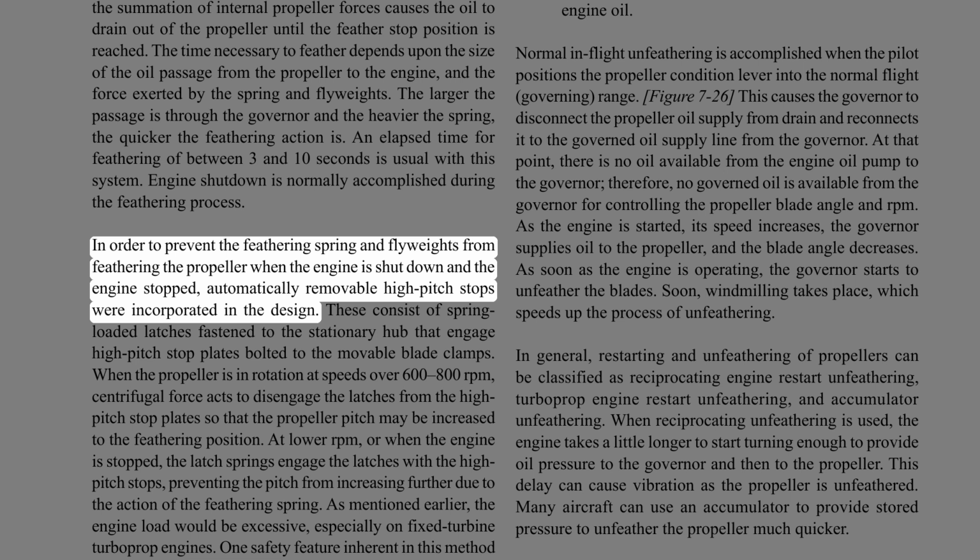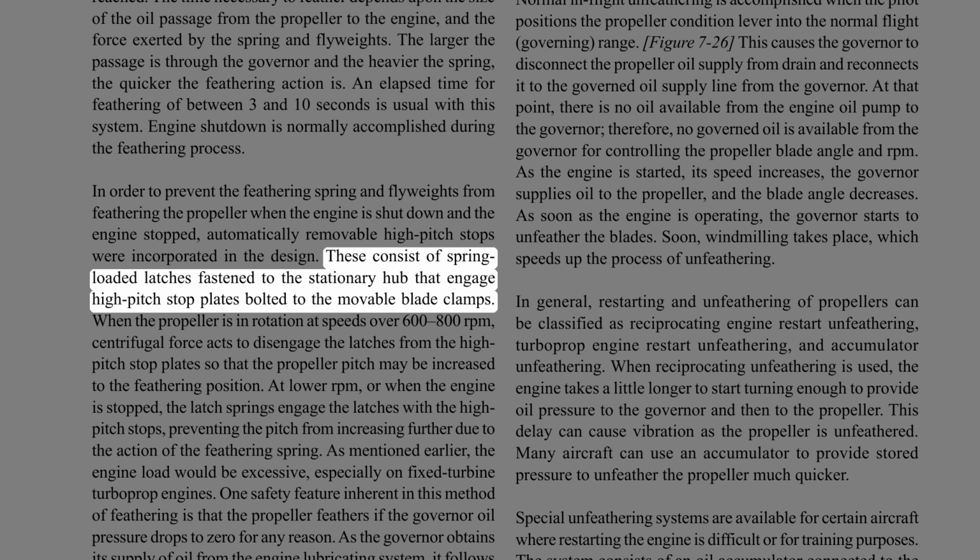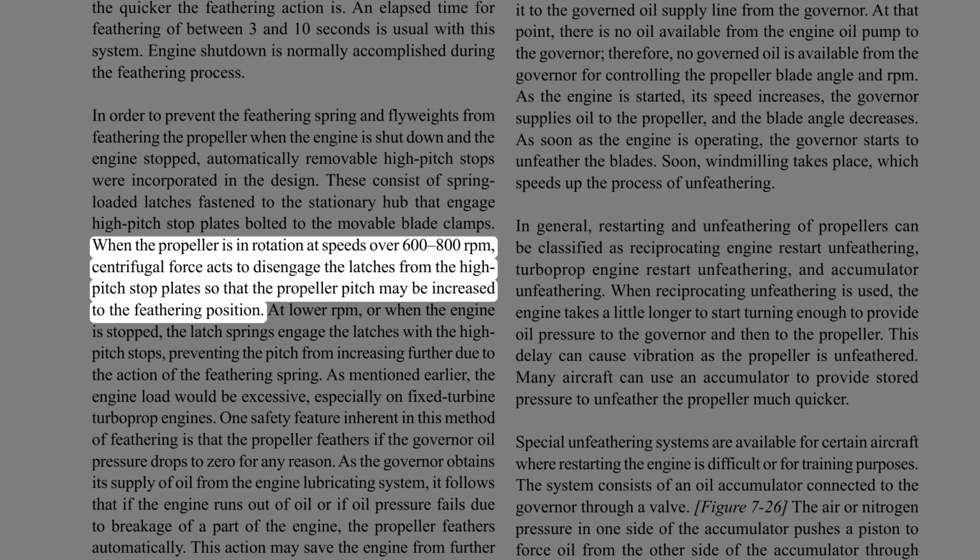In order to prevent the feathering spring and flyweights from feathering the propeller when the engine is shut down and the engine stopped, automatically removable high-pitch stops were incorporated in the design. These consist of spring-loaded latches fastened to the stationary hub that engage high-pitch stop plates bolted to the movable blade clamps. When the propeller is in rotation at speeds over 600 to 800 revolutions per minute, centrifugal force acts to disengage the latches from the high-pitch stop plates so that the propeller pitch may be increased to the feathering position.